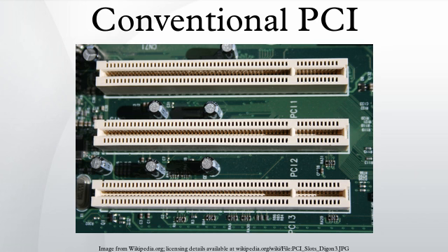The PCI bus requires that every time the device driving a PCI bus signal changes, one turnaround cycle must elapse between the time the one device stops driving the signal and the other device starts. Without this, there might be a period when both devices were driving the signal, which would interfere with bus operation.